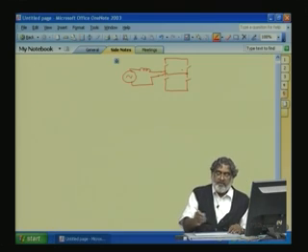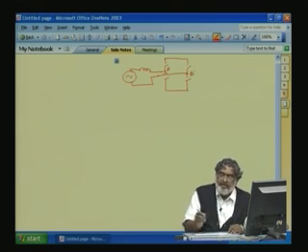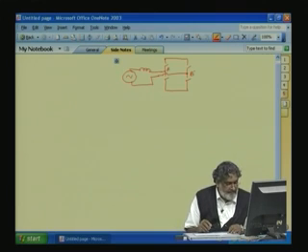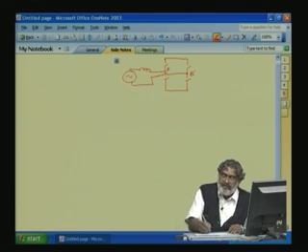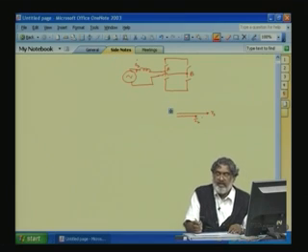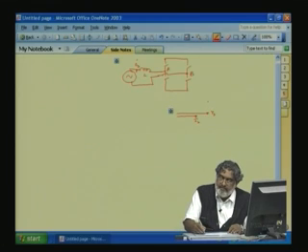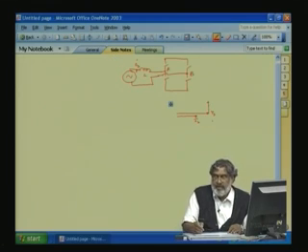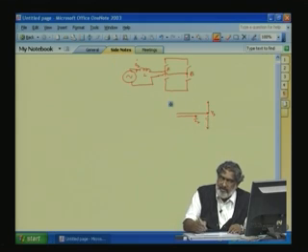Here, this is our A and this is B. Now, according to the phasor diagram, with unity power factor, this is Vs and this current Is is in phase with Vs, and the drop across inductance L will be, for power flow from source to the load, like this, otherwise it will be like this. So, VAB will be like this. This is the VAB.